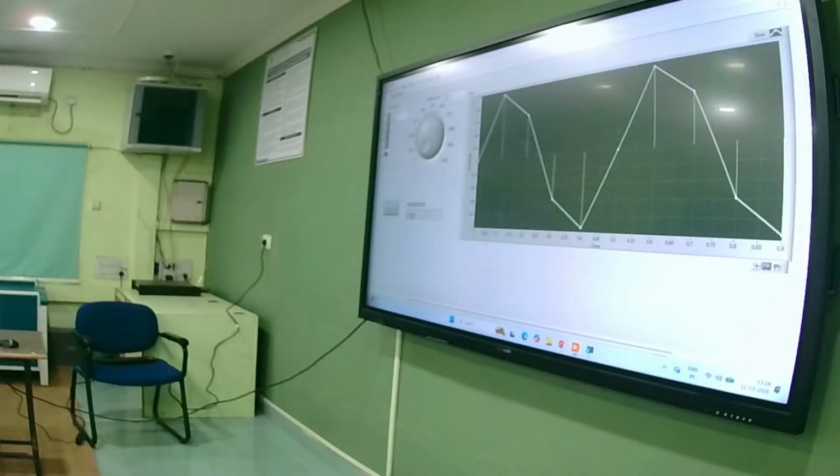If your signal frequency is 100 hertz, you are picking only 5 points of that 100 hertz moving. So always you have to be 10 times faster than your signal, then only you can pick data. Very simple, man. When we throw you a ball at your speed, if you want to catch that ball, how fast do you have to be?